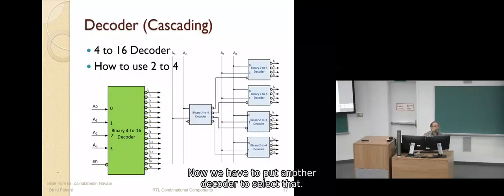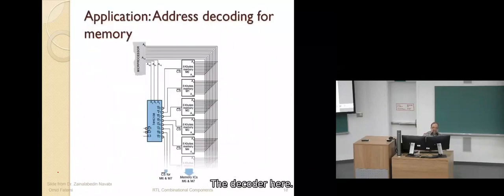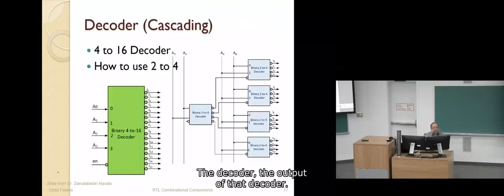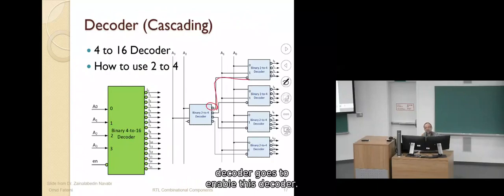Now we have to put another decoder to select that, and the output of that decoder goes to the enable of this decoder.